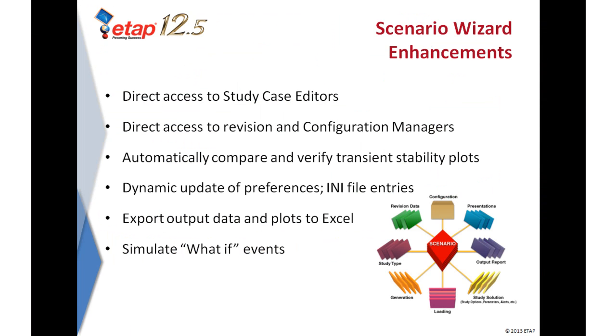The next enhancement I would like to talk about has to do with our scenario wizard. Our scenario wizard now includes the ability to automatically run multiple underground raceway system scenarios with different project files and verify their study results against benchmark reports. We also now provide you direct access within the scenario wizard to our study case editors and our revision and configuration managers.